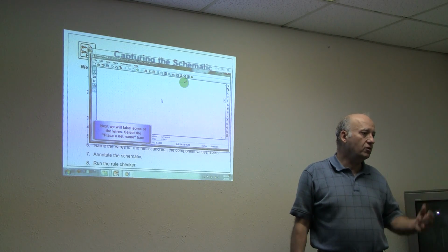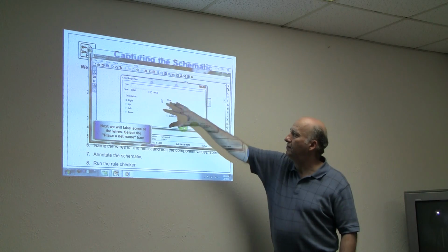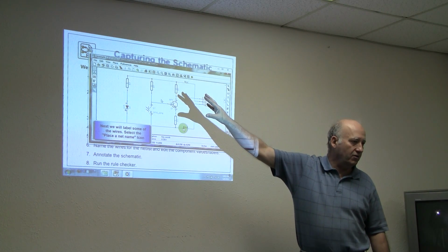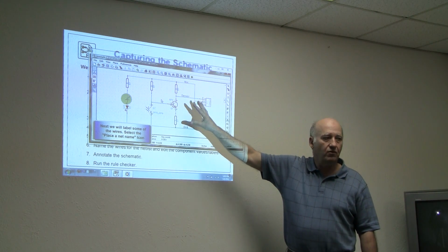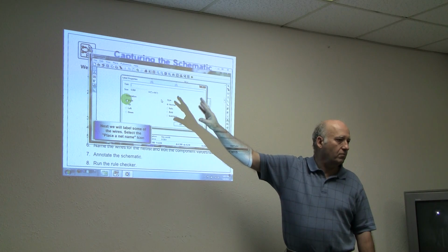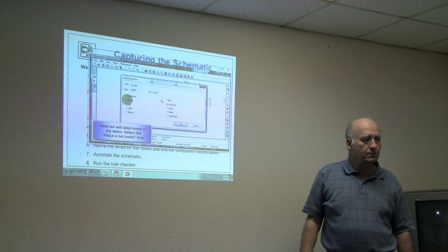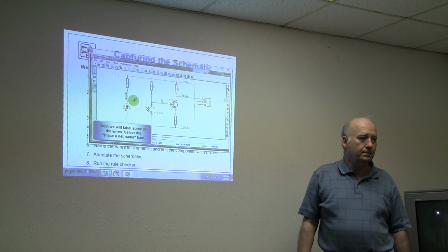But where you do run into it is I do use a lot of connectors. So I might have 3 sensors very similar to this on the same schematic page, all right? And then I have to use the power flags basically to tell them that they're the same thing. Okay, because I ran across some things that I didn't really understand well.